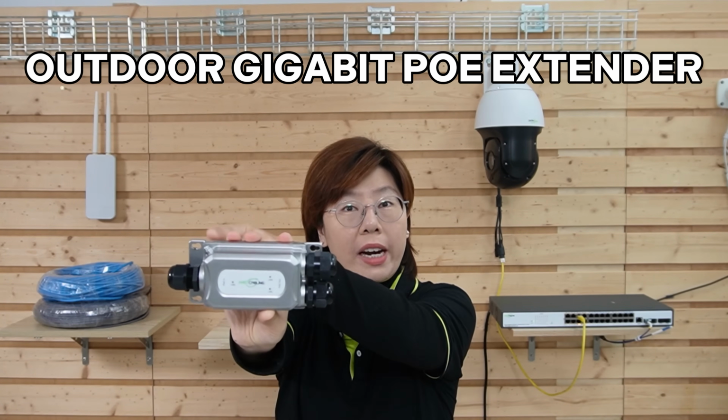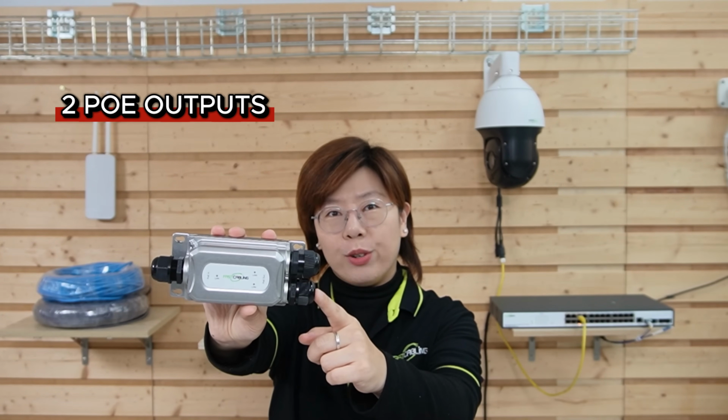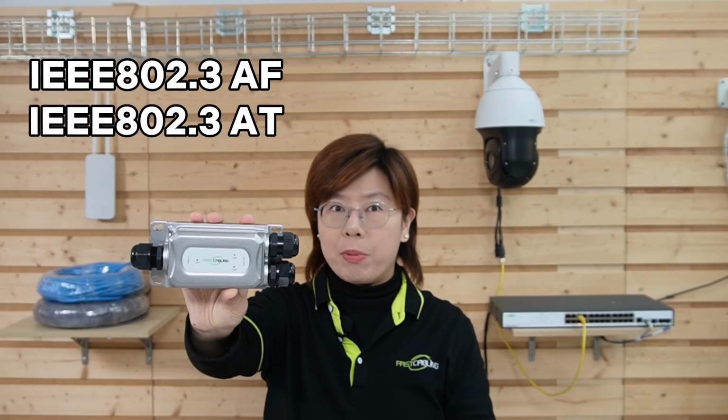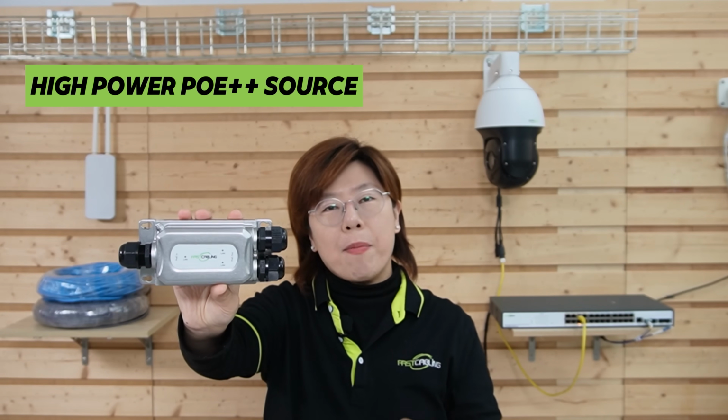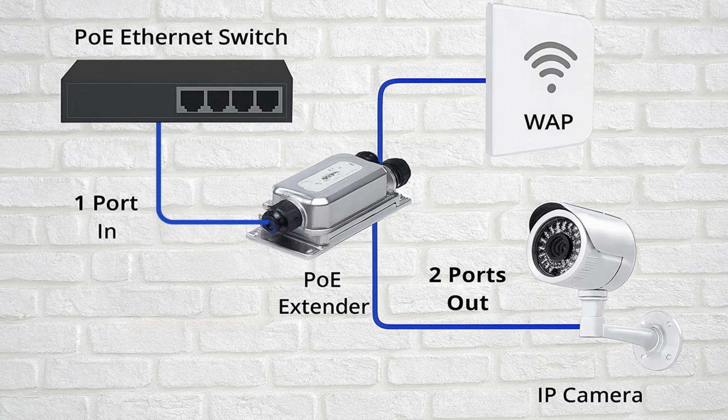The one we're using today is our outdoor 1-in, 2-out PoE extender. It takes one PoE input, then gives you two PoE outputs, and it's designed for gigabit data. It can also work with 802.3 AF, AT, and BT standard PoE. With a high-power PoE++ source, it can deliver up to 60 watts in total, 30 watts per port, which is perfect if you want to fit a Wi-Fi access point and maybe a nearby camera from a single extender.